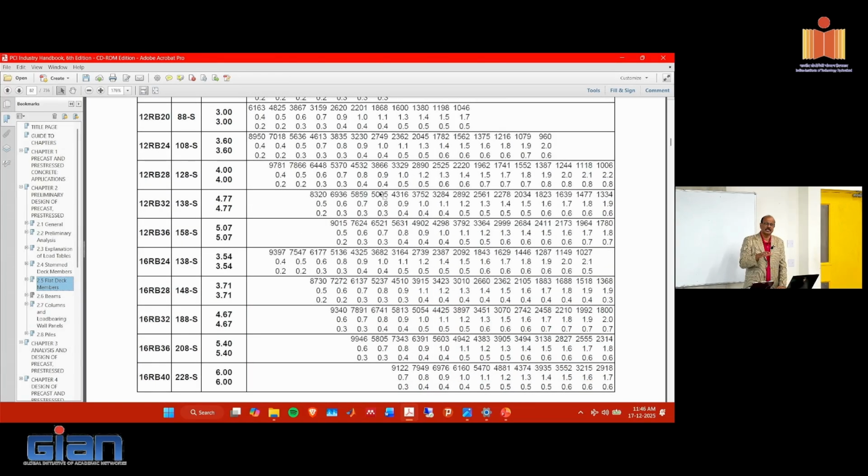But if they happen to have a project where for some reason they want to do something longer or different, then they will have to talk to the precaster. It's not that they're going to ignore it, but they have to make specialized formwork. Typically, I think I mentioned yesterday, the precaster would use steel formwork. The double hollow core, for example, I showed how the positioning of the strands are. They're all fixed in the plant. So you don't move things around from construction to construction.